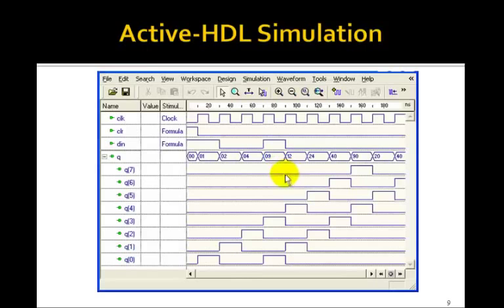So here's a simulation. Now this is just a simulation of the module, the shift reg 8 one. So here is D in. We show D in as sort of 1, 1, and then off for a couple, up for 1. And you'll see it gets shifted into Q0, and then that pulse will get shifted over to Q1, Q2, Q3, 4, 5, 6, 7. So in the top level design, these would be connected to the LEDs, and you'd watch the LED lights shift through.